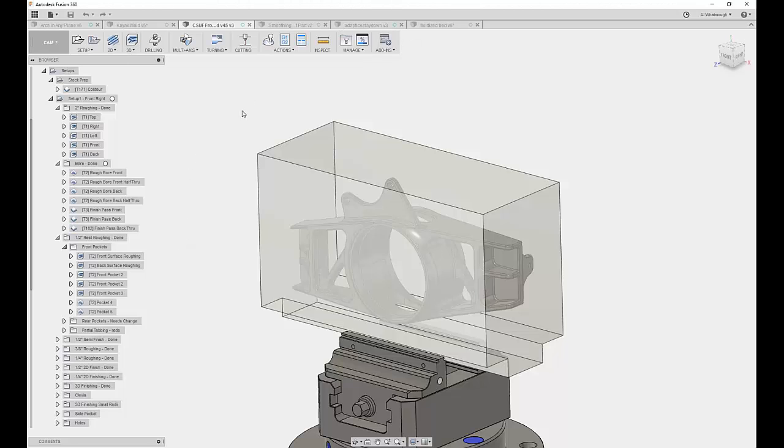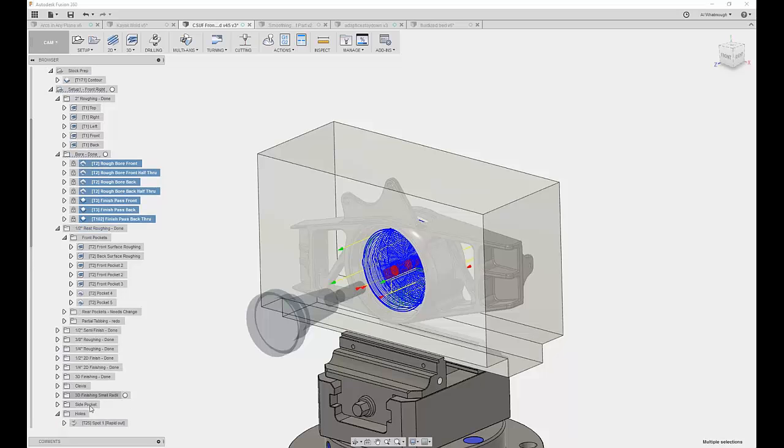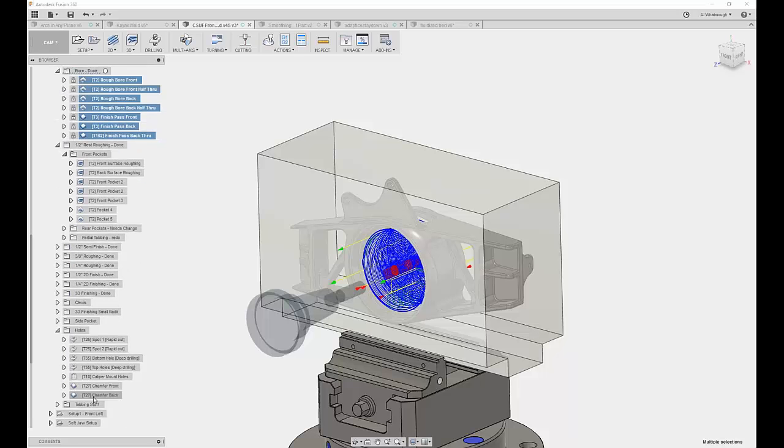While we're staying on that same topic, another thing you might do when you end up with a lot of toolpaths and you're bouncing back and forth is take a series of operations. If you don't want them to regenerate, you can right-click and you can protect those operations. So if you right-click and protect the operations, then they're not going to get regenerated. They're not going to get flagged as dirty. You're not going to have to worry about some of those other recalculation problems if you're down finally working on the hole down at the bottom and you want to almost break the associativity. It's not fully broken because you can unprotect and you can still recalculate later, but a great way to manage large amounts of toolpath. I know a lot of the files I see from Tim, he's in that habit because when he's finished something, he wants to know that that's done and kind of move on to the next step.